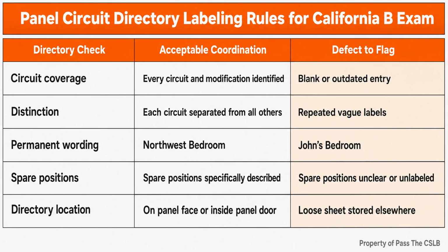That distinction matters because the tempting shortcut is to treat a breaker as a replaceable switch with a number on it. It is not a number I casually change to make a problem disappear. When a rating appears inconsistent, when a circuit has been modified, or when a panel schedule does not match the work, I treat that as a coordination issue. I do not guess at conductor ampacity, calculate a new breaker size, or redesign a circuit from the field. I compare the installed work with the approved information and bring the electrical contractor into the decision.